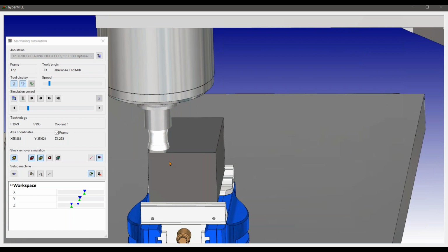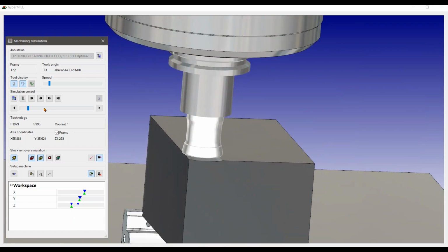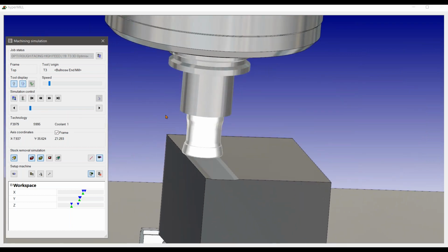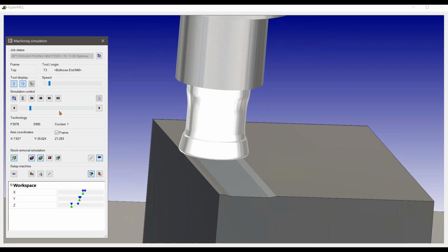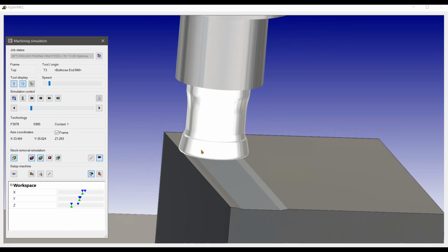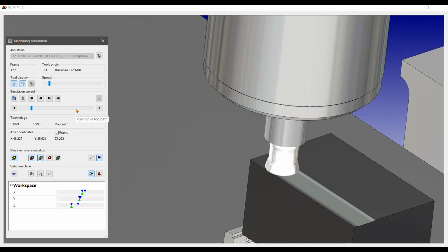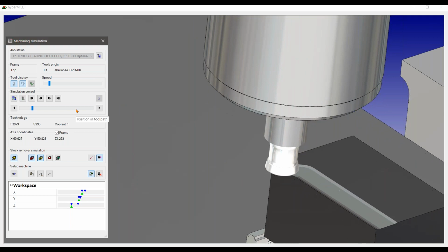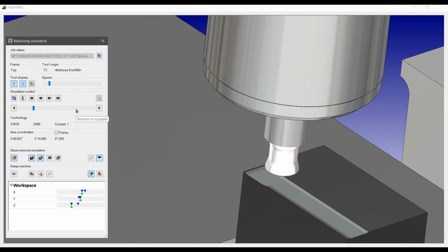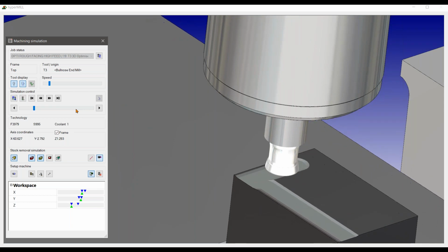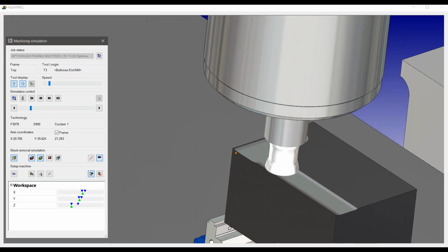Now this tool path is a special tool path, and it's been developed to leave no material behind. We're looking at a full engagement here, and it actually works off a cusp height. When we get to this corner scenario, the tool spikes off and then maintains cut direction. That spike is to ensure that no material wedge is left in the corner.